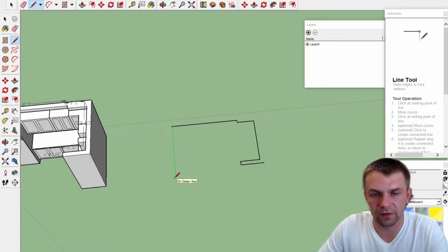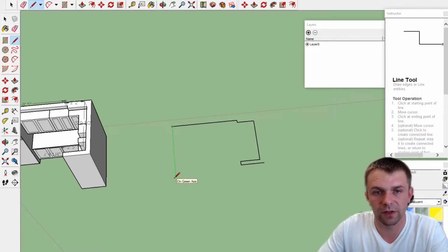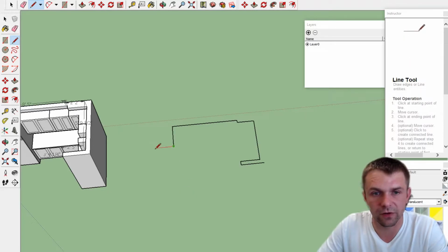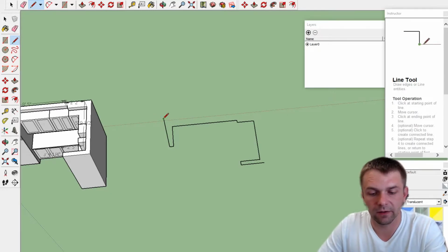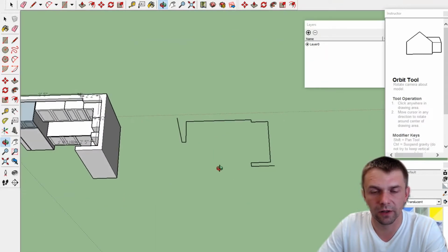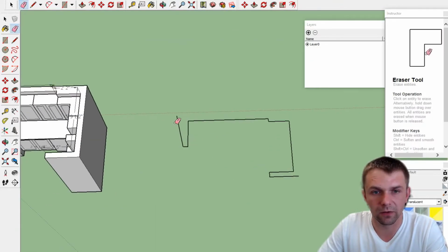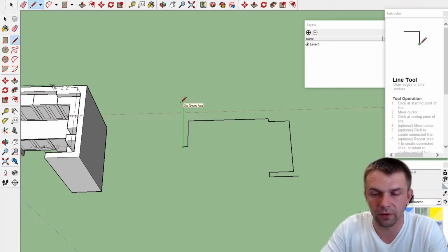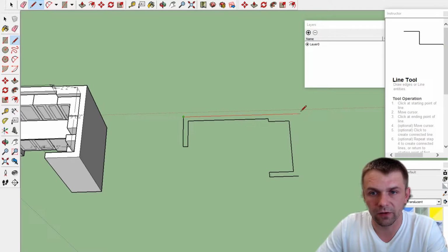This is a small condo kitchen, so this wall particularly continues. I'm just gonna make it 36 inches for this drawing. We go back 6 and we go back, and you see the blue that just appeared, so if I click that, press escape and orbit, the line went vertical, and that's not what I need. So we go erase, L for line, 42, and then we continue this way.